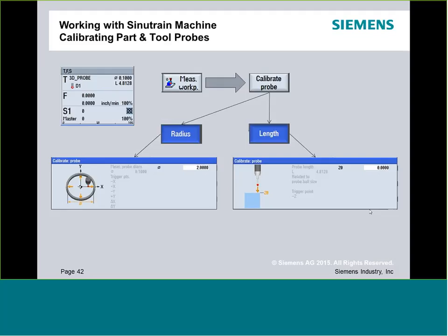Now, it's just going to go your normal pick distance. Obviously you're never going to get a unique trigger against something. It's just going to go to whatever the default parameter was in our MDs for the pick distance, but it will run a full cycle. So if you're in auto, maybe you want to just validate the syntax of your probing and get some of the mechanism to work. All that can be done, but you do need to make sure you calibrate the probes first.